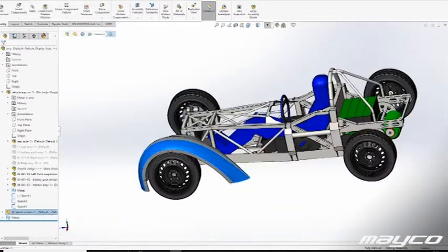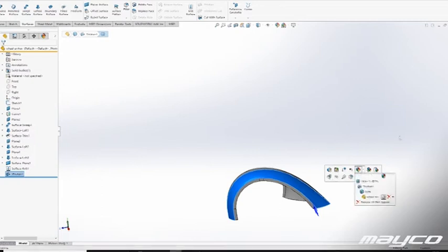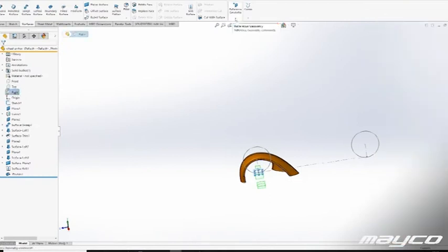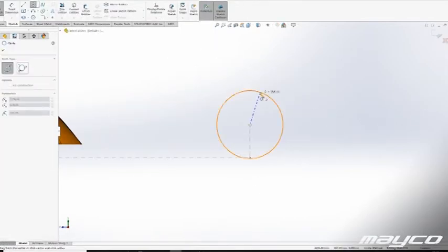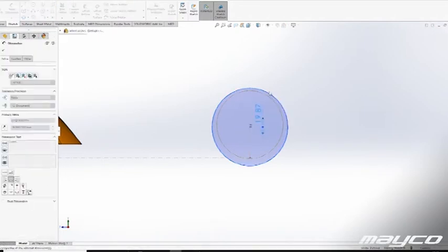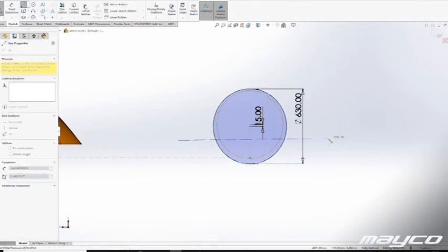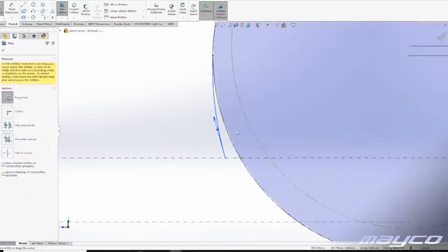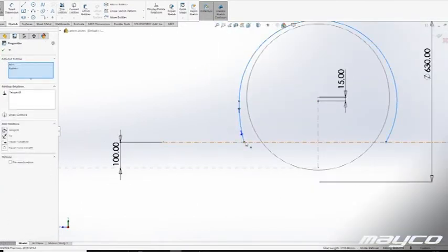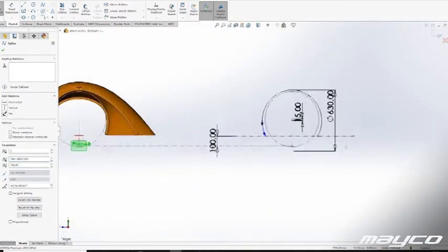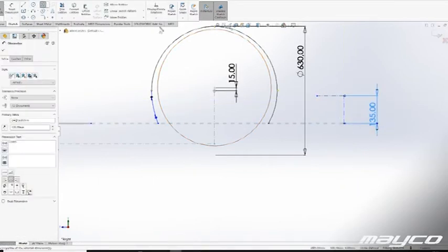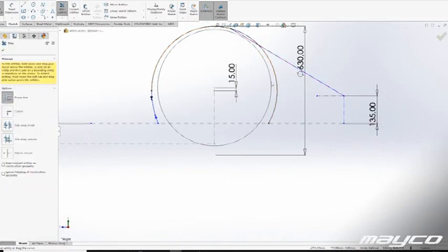Sometimes you really want to be free and do what you want, but especially if you go into detail engineering with a surface model for a car, for example, you have to work around a chassis or a suspension arm, or you have to work around a crash zone or a seat or whatever, and you have to work very accurately with dimensions, etc. So whichever way you do, work very precise, work very accurate, and the more you work with dimensions and the more accurate you are, the better the results will be, and the easier it is to have a good chance of the surface model being able to convert to a solid body.